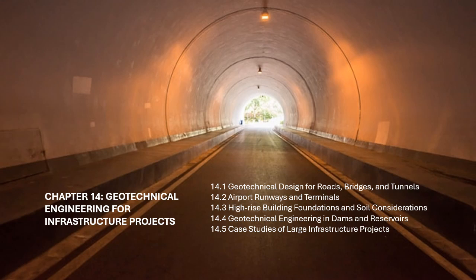Airfield expansion and modification. Airport projects often involve the expansion or modification of existing runways or terminal buildings. Geotechnical engineers must assess the condition of the existing soil and foundation systems, determining whether they can accommodate the additional load or if improvement techniques such as soil stabilization or deep foundation replacement are necessary.